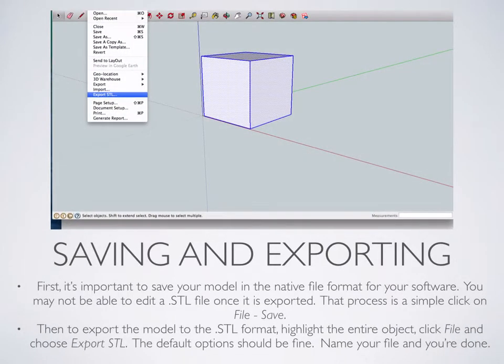Now, the first thing you want to do before we save this as an STL file that can be exported to a 3D printer, is save a copy of your model in whatever native format your software uses. SketchUp has a native format, and if you save it in that format, then you can come back and edit your model later if you find out that there's too much detail or there's something that's not printing quite right. And that's pretty simple. You just go up to File and find Save. It's like any other software, Microsoft Word or anything like that.